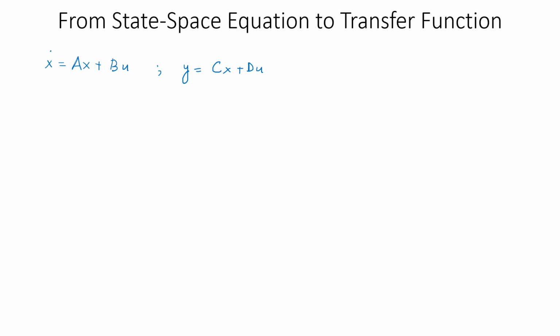And for that, we have to start from here, and you can observe that the first term is the x dot term. So I can make you recall that for that we have just observed that x dot is equal to dx by dt, and this is going to be equal to, in the way we have written down, s X of s. So that would mean that for any single derivative term, you are going to add s corresponding to that expression.